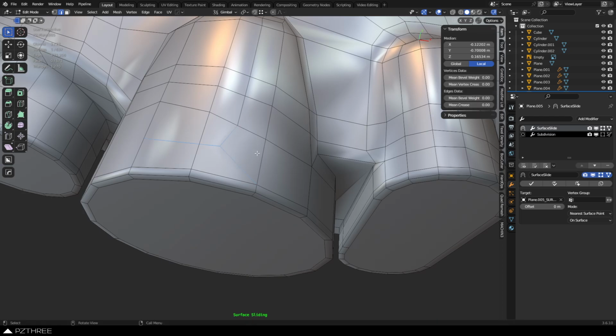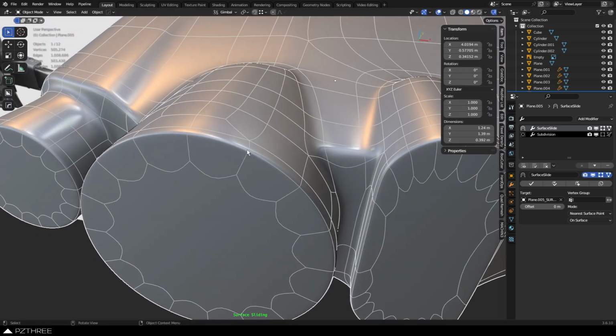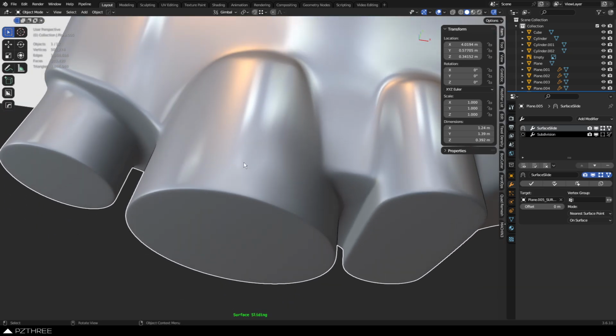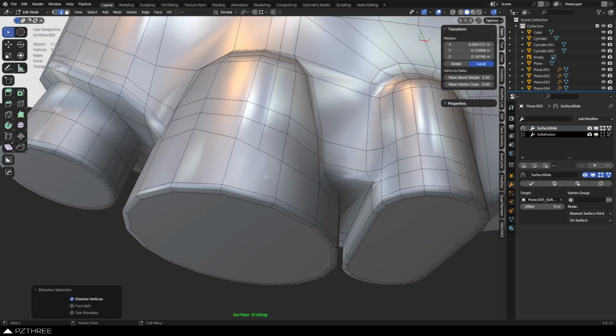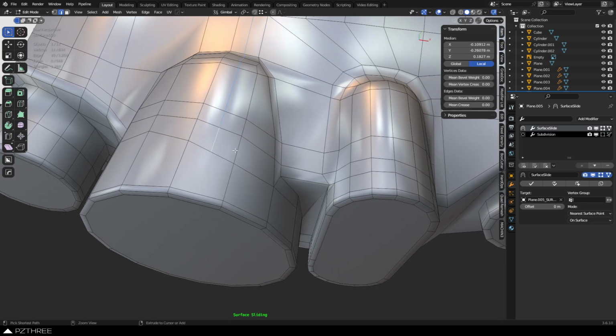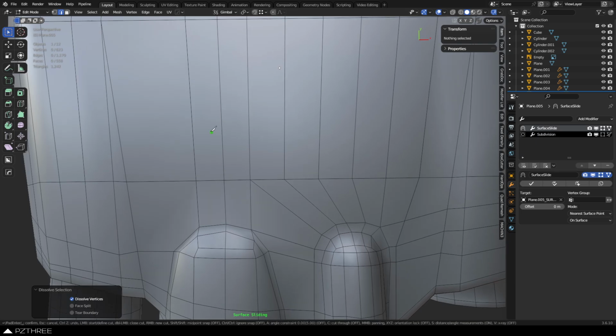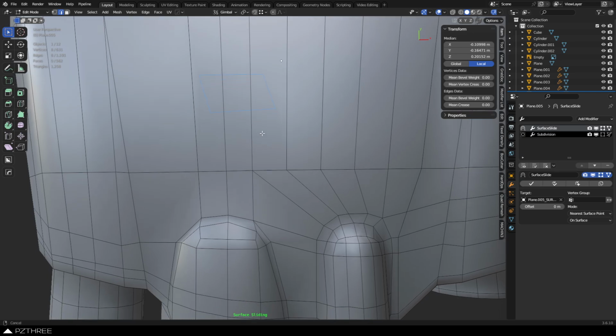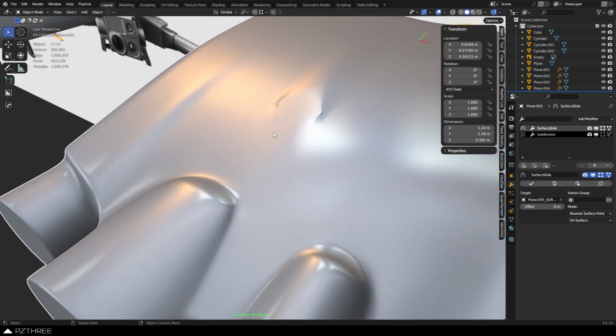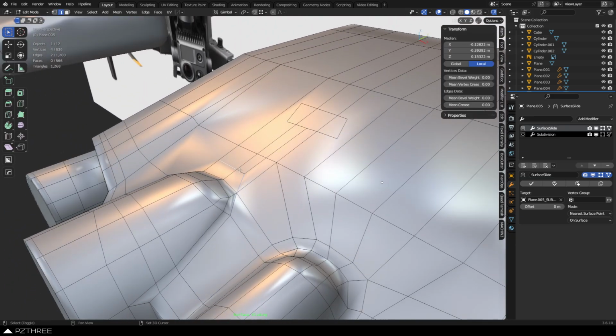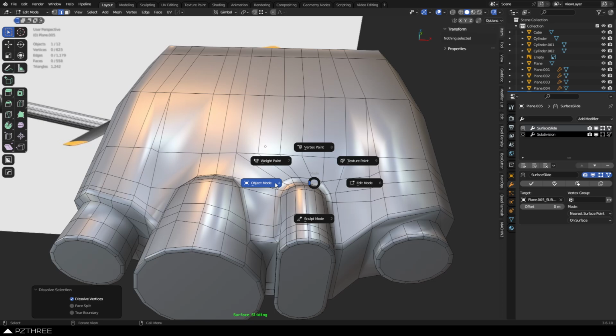Is that a possibility? And of course, we're creating a pole, so it's also going to create a little weird topology patch here. Cylinders are very picky. Curvy shapes are very picky. They like the quads. They don't like the additional edges going through them. So if you ever had to do a detail over here, you're just cutting something in, and you had, for whatever reason, an edge going down in that direction, you redirect it maybe back here on the flat face, not over there. And that might give you a better result. So you can see, you can do things like that. Just create that little end pole basically, and we'll get rid of all that. We don't need it. All right.